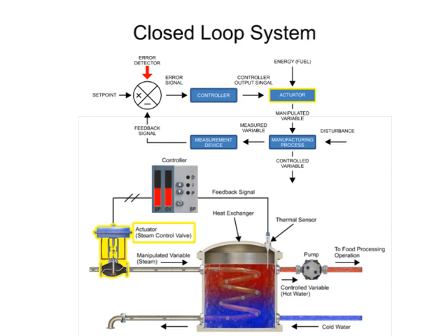The flow valve represents the actuator, where steam flow is controlled. The amount of energy or steam in this example, altered by the actuator, is the manipulated variable. Manufacturing process is the operation of the heat exchanger to control the physical variable.